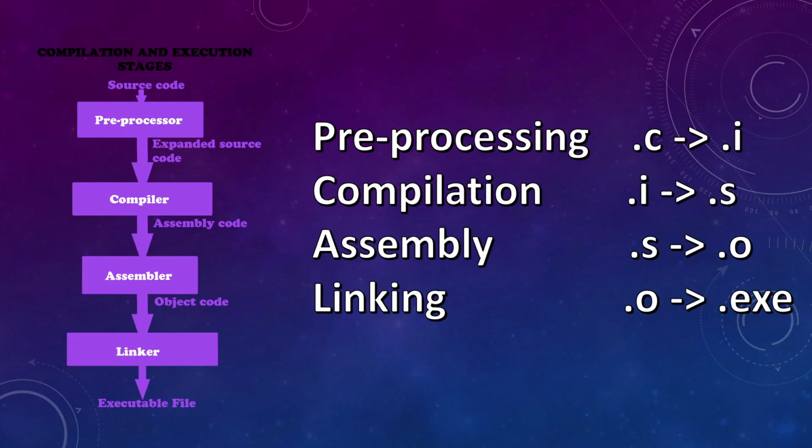Next comes the flashing process. Once the hex file is created, the next step is flashing. Flashing means loading the program into the flash memory of the controller. This is done using a programmer or a development board tool. Once the file is written, it remains stored in the memory. When the power is turned on, the controller reads these instructions and starts executing them.